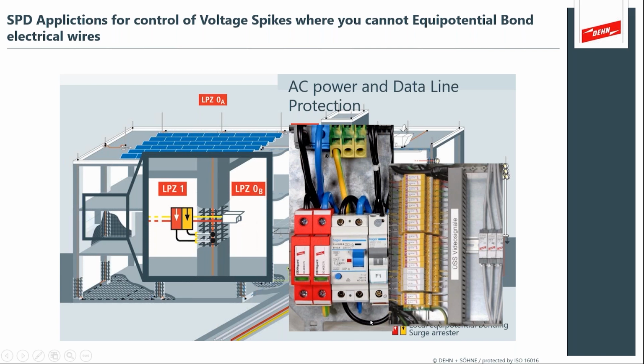The lightning currents are coming backwards from the earth, and it's inducing it into your electrical control panel, essentially upside down. It's coming from that ground potential rise, and those voltages are trying to break into the dielectric of the electrical wires, and that's what your surge protector does: it prevents an overvoltage from breaking down the dielectric of sensitive computers, of your sensitive control systems and cameras.